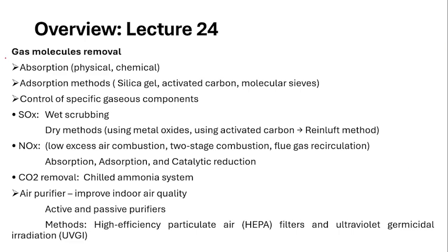And next is the gas molecules removal. These gas molecules can be removed either by the absorption or by the adsorption method. Absorption mainly happens in liquids, through physical or chemical interaction. And the adsorption method uses solids. Over the solid, the gas molecules will be present, just adsorbing over the solid particles. These solid particles can be silica gel, activated carbon, or molecular sieves. These can be used in this method.